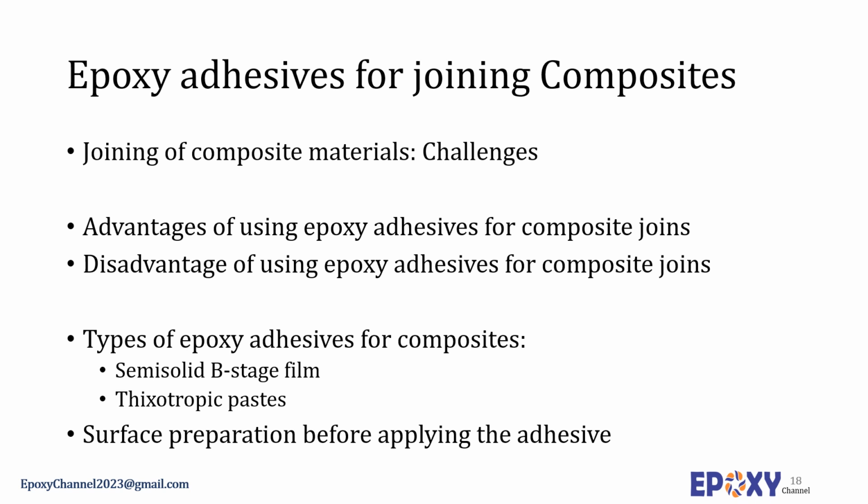Paste adhesives are supplied as either one or two component adhesive systems. They can be used in applications where pressure cannot be applied. Some two-part pastes cure at room temperature and some others do not. Epoxy, urethane, and acrylic adhesives are available as paste adhesives.